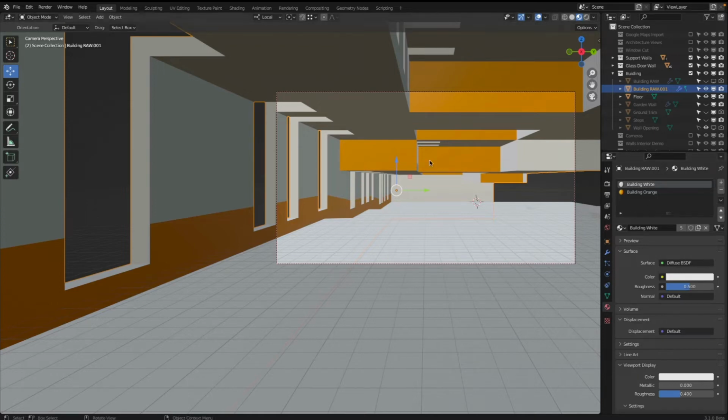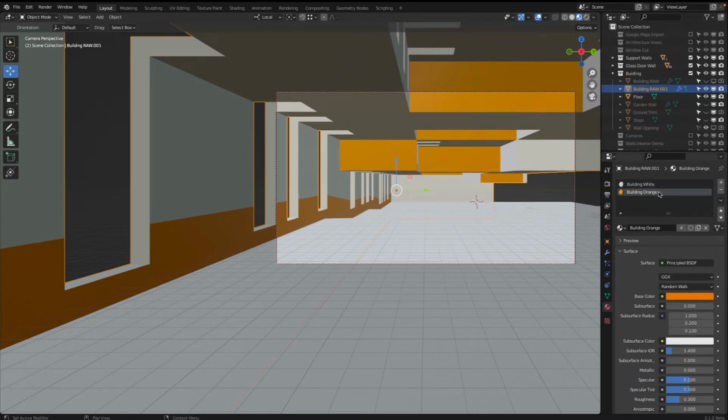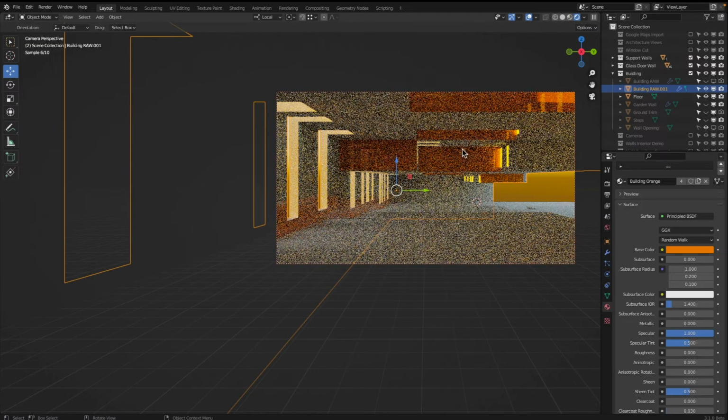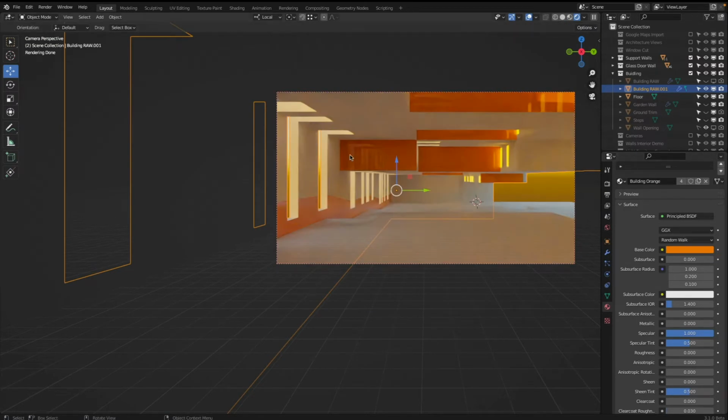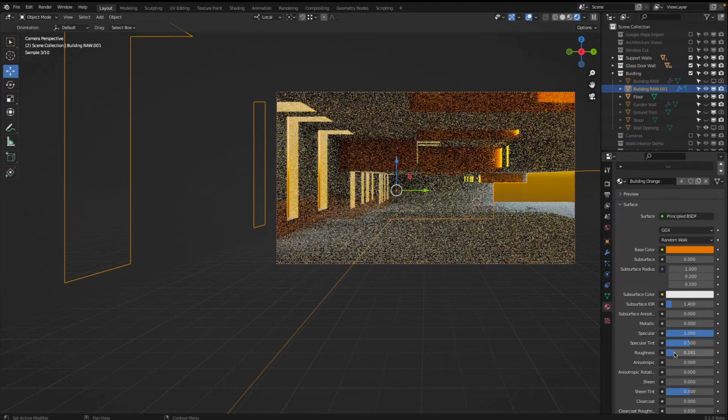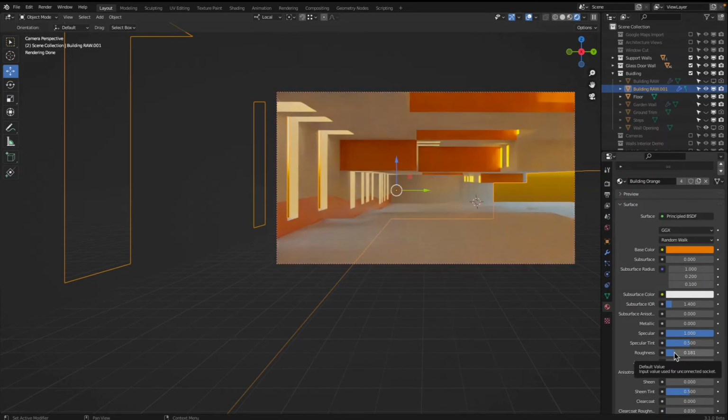And just again, just to reiterate, you have matte material, you also have glossy material or semi-glossy. So if this should be high glossy, then this is a normal BSDF, and we go specular, and the roughness makes sure if this is now really like plastic glossy, there you can see the reflections on it. Or if we set specular to 0 it's matte. If it's really reflective, okay, but if we then increase the roughness, the reflectivity is there, but the image is more diffused.